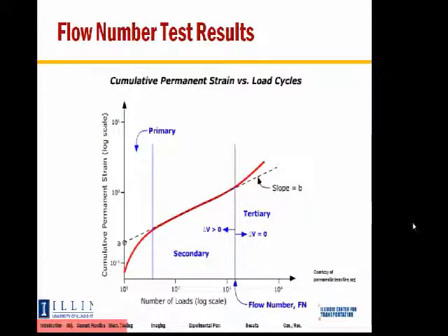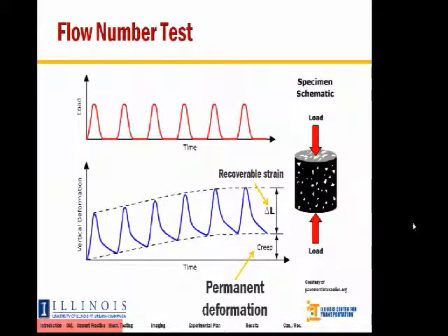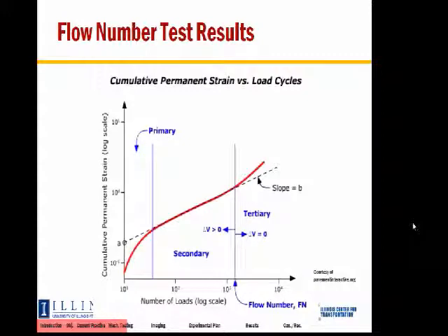So what we end up doing on a larger scale, if I go back to the previous slide, if we take the strain response here over several hundred cycles, in some cases a couple of thousand cycles, if we look at just that permanent deformation or that accumulated creep that happens one cycle at a time, we actually end up with a creep curve. Okay? The term creep is used by people in the HMA industry a little bit loosely. If people are coming from a strict mechanics background. Okay, that creep again is just that accumulated permanent deformation.